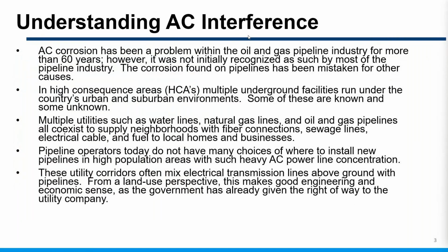When I first got into corrosion in '69, they were on top of their game. They were already using lightning arresters and spark gaps on a 30-inch line, and this was done in the '50s, by the way. It was set up based on proximity within 10 foot. If the tower leg was within 10 foot of the pipeline, they installed these devices.